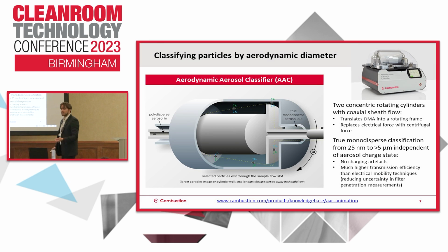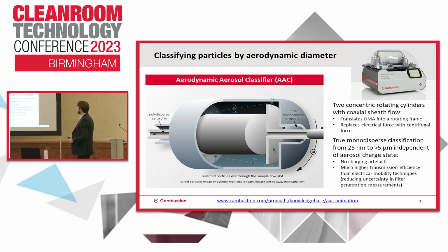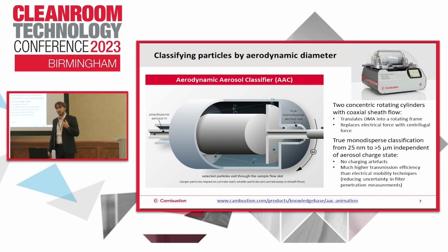So very recently, there's a new technique that's been introduced. This instrument was launched in 2016. It replaces the electric force in the DMA with a centrifugal force in two concentric spinning cylinders. So for a set ratio of centrifugal force to aerodynamic drag as particles move outwards in a spinning cylinder, you select the particle size you want. And the huge advantage of this is it doesn't depend whatsoever on the charge state of the particles, and the aerosol is truly monodisperse. You are only passing the particles of the size that you require for your filter testing.